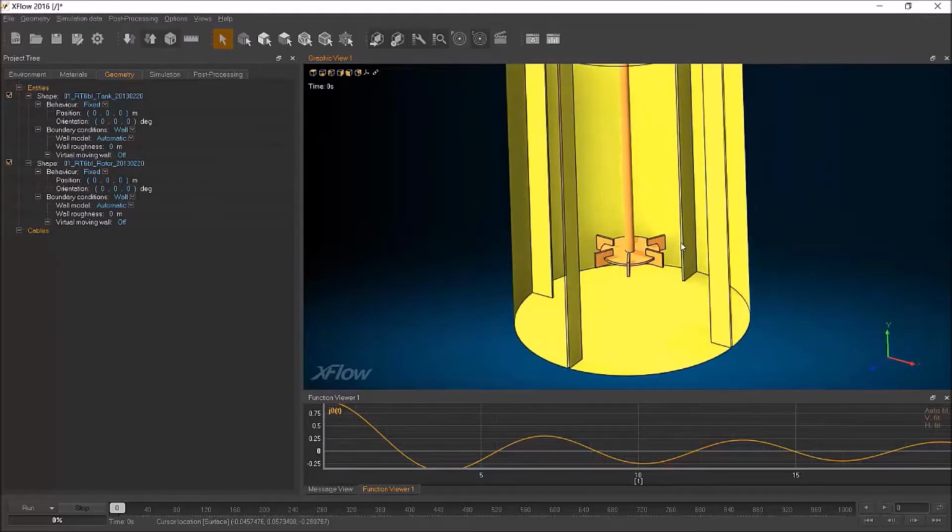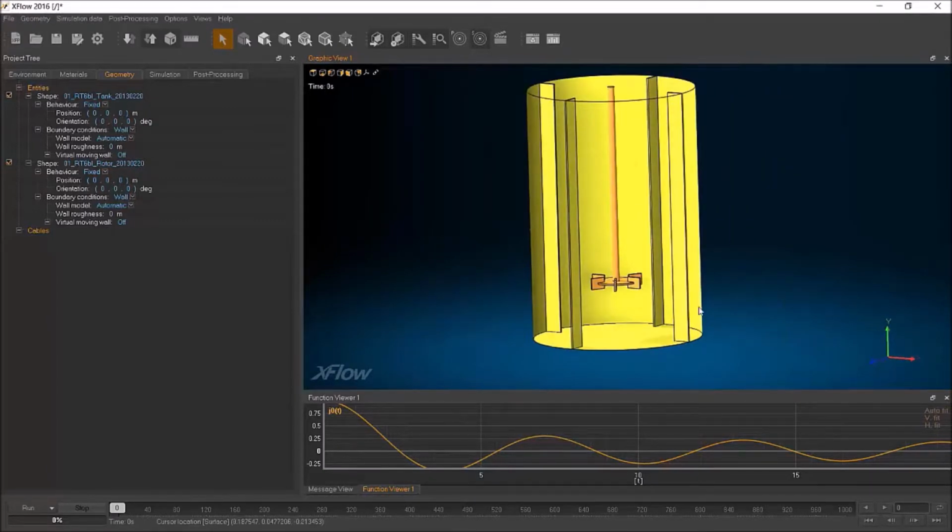And now we've got defined, let's say, our volume of fluid being inside this and outside there. I can just define my motion of rotor. The only thing I have to do is switch from fixed to enforced and define a law where we prescribe the rotation speed. So in that example, I'm going to give minus 500, or well, actually the sign doesn't really matter because that turbine is just symmetric. So just 500 RPM, so that could be 360 degrees per second, and times t, which is a temporal variable.